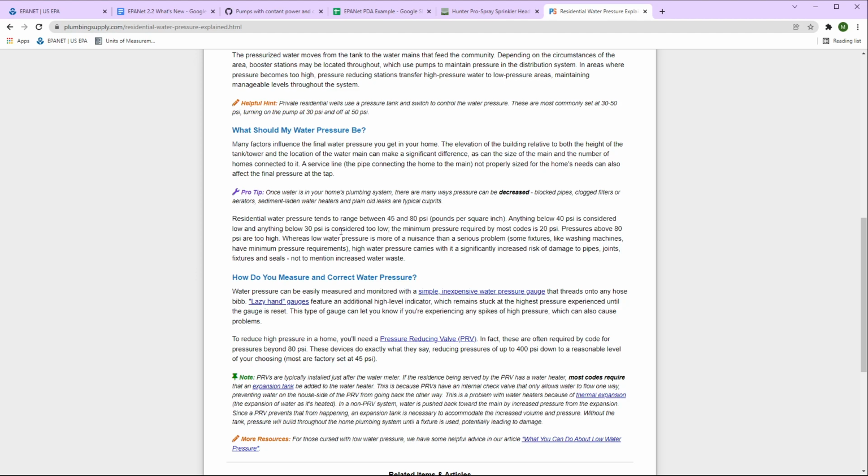Usually the municipalities and utilities that I'm used to and the state water quality boards say that under emergency circumstances, you've got to maintain 20 psi or more at every connection. The criteria we use in our utility is state mandated 35 psi, but we shoot for at least 40 psi everywhere in our network. So it's kind of something you have to think through.